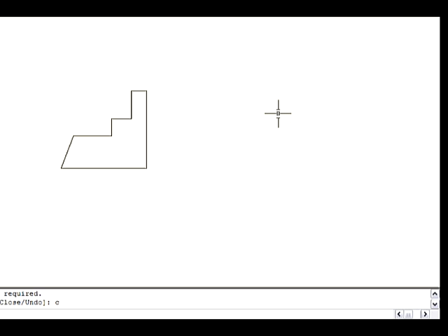Let's see a few other tips and tricks for effective keyboarding. Use the Escape key to bail out of the current operation. There are times when you get confused about what you're doing in AutoCAD or what you're seeing in the command window or the dynamic input tooltip. If you need to bail out of the current operation, just press the Escape key one or more times until you see a blank command line. Command at the bottom of the command window with nothing after it.